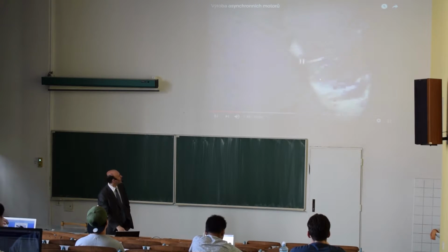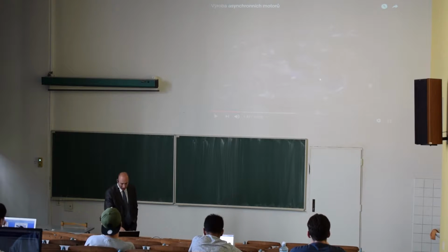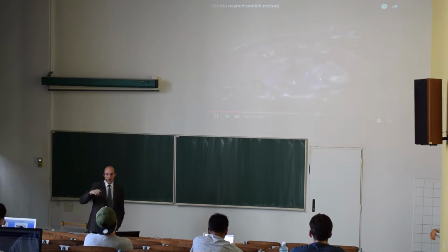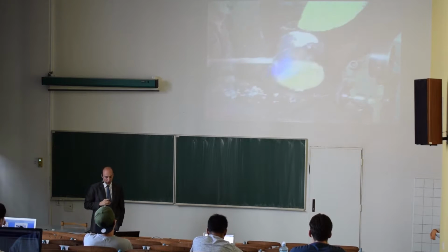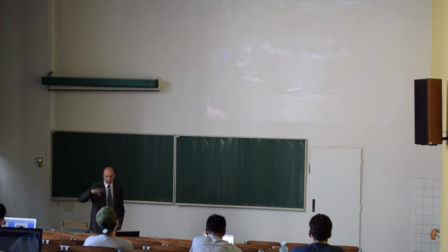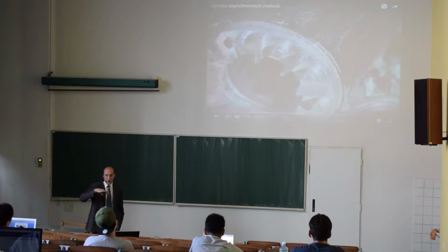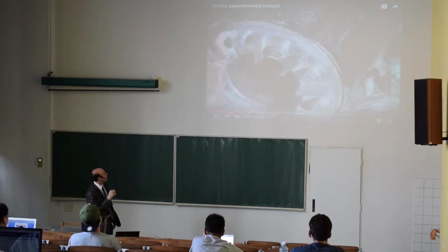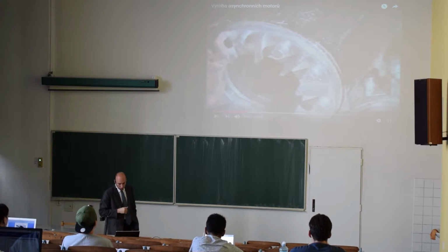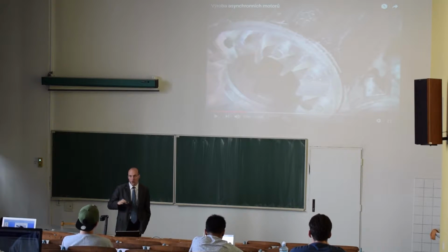So now you see he has inserted this packet into a machine where he will pour molten aluminium inside the slots of the rotor and press it inside. So it's in one operation. He has poured the bars inside those rings, and then here you see the blades of the fan that will provide cooling for the induction motor. So it's very easy to produce compared to DC motors.